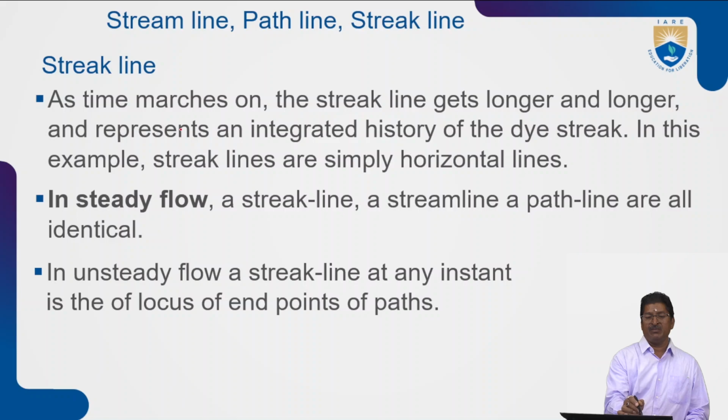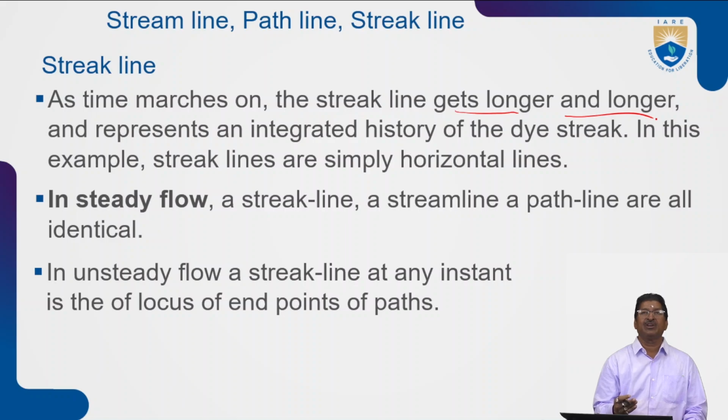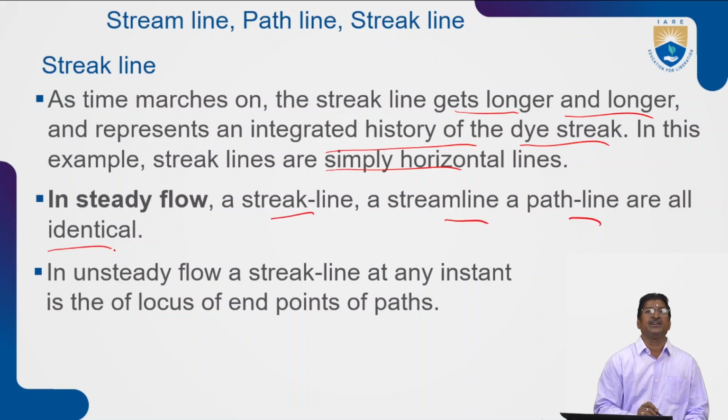As time marches on, the streak line gets longer and longer. It represents the integrated history of the dye streak. In this example, the streak lines are simply horizontal lines. In steady flow, streak lines, streamlines and path lines are all identical.